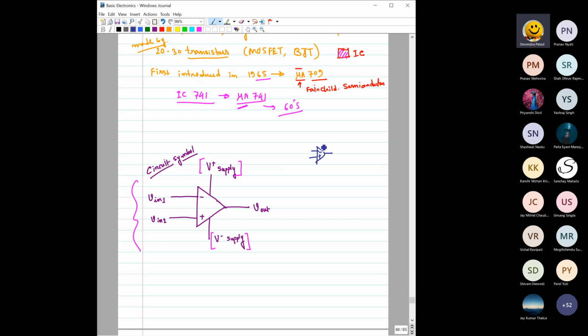In many cases students forget to connect them, and then they find their circuit is not working as expected. After inspection, it is found that the student forgot to give the proper DC bias to the op amp. So remember that you must always apply the plus supply voltage and minus supply voltage.